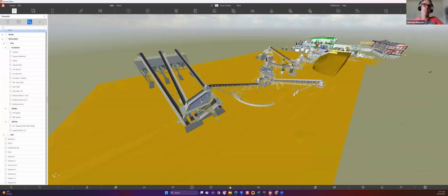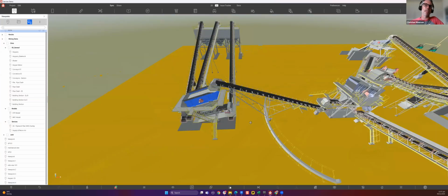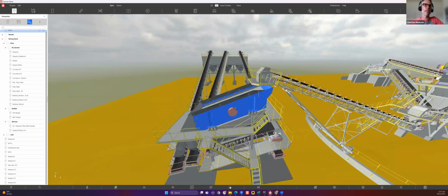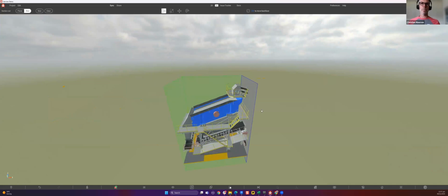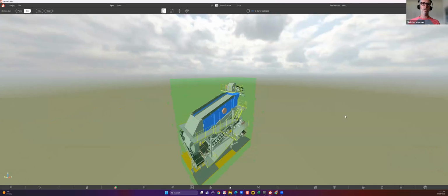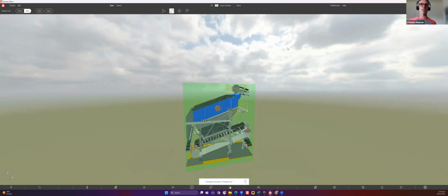I've also got a box tool. This way to engage that, say I want to have a look at this hopper here, just select the element and then basically hit your scissors, you cut, and then I can start to navigate around this particular element like so. So if I'm interested in just viewing this object, again, save it into my viewpoints. I can come back at a later date. Various other tools in here just to scale boxes and move it around or rotate if you want.